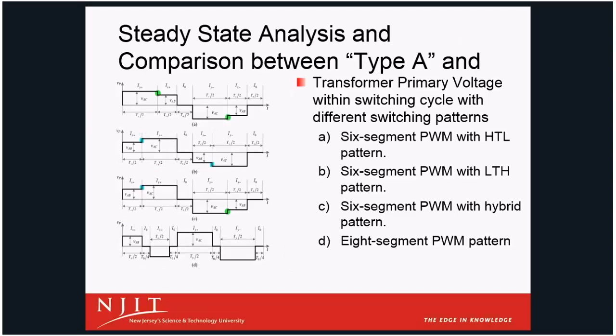In order to do so, what the rectifier does is it synthesizes, or switches, your voltages to get your different line-to-line voltages across the transformer primary for rectification. For each active vector, there are two possible switching states, as I mentioned earlier.